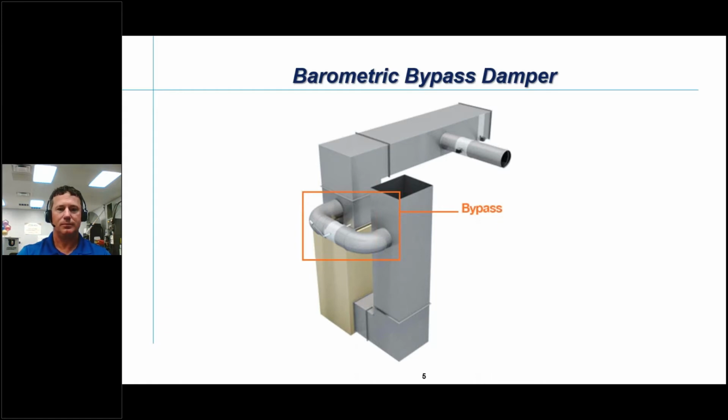But like you said, if you put a dual port manometer on it, Clifton, you can actually keep the static pressure where the system was designed, which is a 0.5 or below. Right. So exactly. That's how we were taught to adjust the barometric bypass, to maintain a 0.5 or lower static pressure on the blower. It's all about controlling that external static pressure. That's what we dove into last week, talking about how external static pressure affects these blowers.